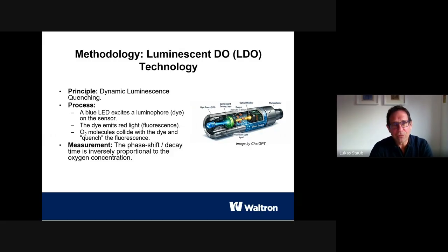And because we're not looking at a membrane, well, there is a sort of a membrane, obviously, in such a sensor that contains the luminescent dye, but this is a ceramic membrane, if you will, which is much less prone to mechanical damage. Obviously, if there's particles around, there is no disturbance to be expected from the pressure or temperature shifts. So much more stable measurement.